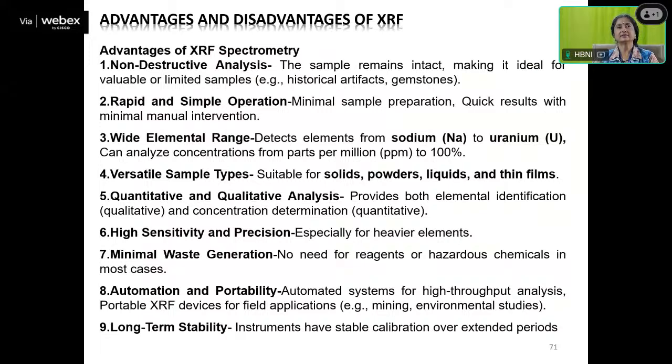So now, advantages and disadvantages of XRF. Now, it is a non-destructive analysis. The sample remains intact, making it ideal for valuable or limited samples, like any historical artifacts, gemstones, or your ornaments. So it can remain as such. Now, rapid and simple operation. So minimal sample preparation, quick results with minimal manual intervention. Then wide elemental range. So it detects elements from sodium to uranium, and can analyze concentration from ppm to 100% also. So there is a wide range of concentration.